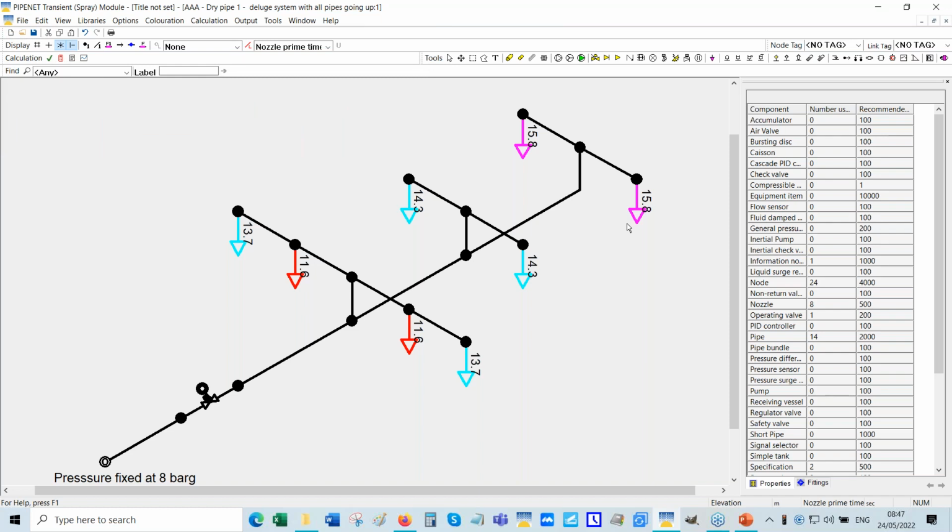So you can see that now there's a little bit more difference. It's 0.4 seconds because there is a bigger resistance to flow through the nozzle. So in this case, maybe even here, what's the difference between 15.4 and 15.8? It is within the kind of variation that you would accept in engineering. But you can see that there is a small difference if you use smaller nozzles.